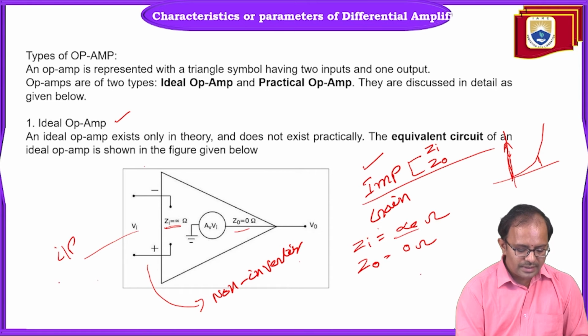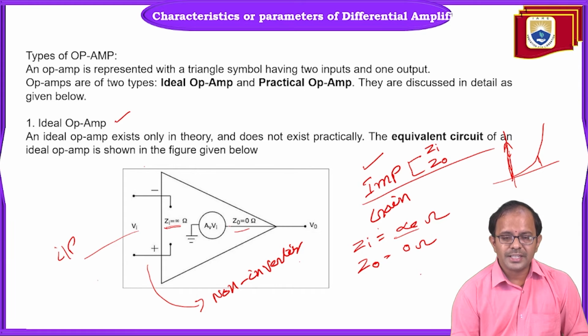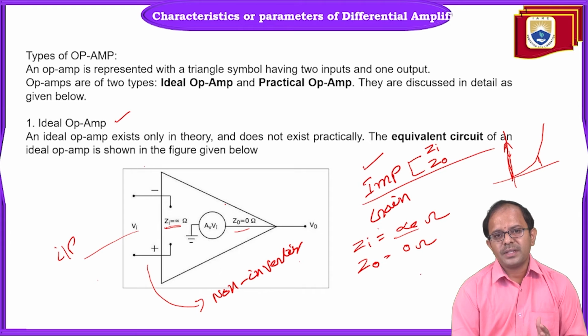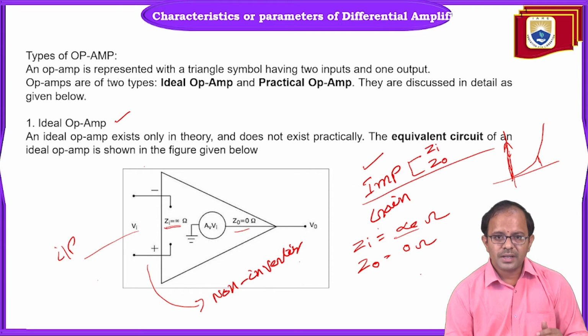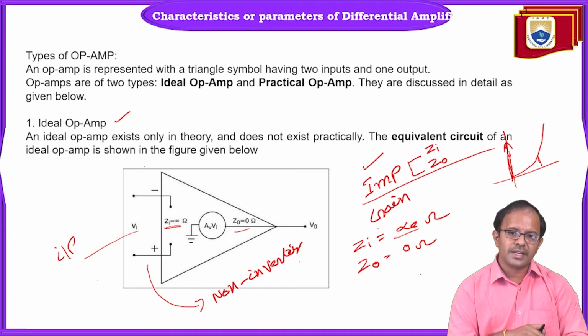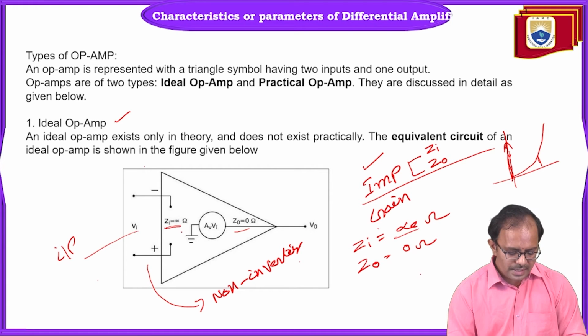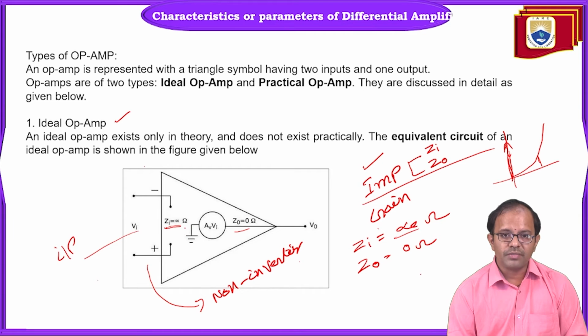Here we are giving some external signal that is going to play with the active device. So this impedance should be sufficiently high so as not to damage this active device, op-amp or transistor, because of the sudden incoming signal from the external ports. So it is always required to maintain the input impedance sufficiently high.